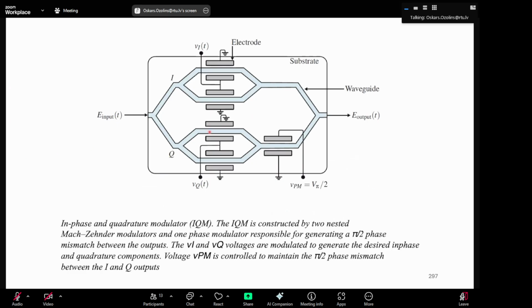This is done with one amplitude modulator. In an IQ transmitter, you have one amplitude modulator, then a second amplitude modulator, one for I and the other for Q. Then you have a phase modulator because you need a 90-degree shift between I and Q to be able to form an IQ constellation, so you need to rotate the constellation. Here you have an I constellation, there a Q constellation, and in that way you will be able to build it. So maybe I'll just draw some example.